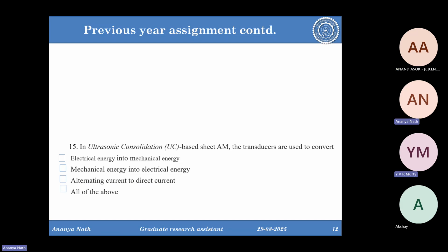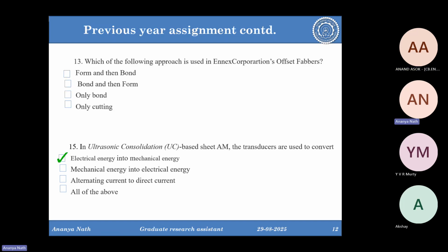The sonotrode is connected to the transducer, so the electrical energy is coming to the transducer, which converts it into mechanical energy and gives it to the sonotrode. Now the sonotrode transfers that mechanical energy into my sample. Think in a reverse way.